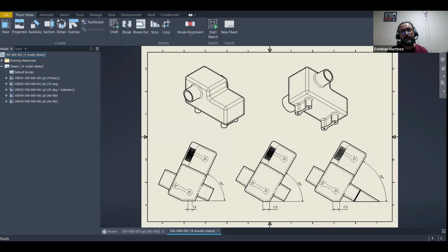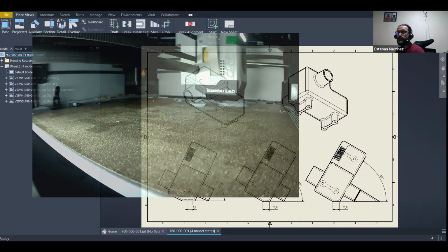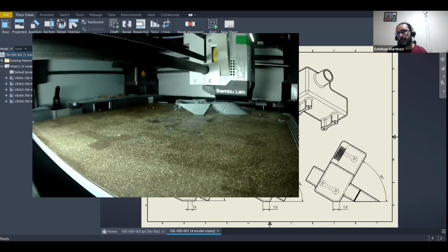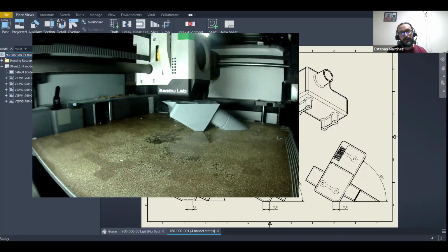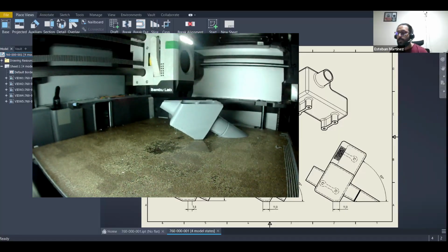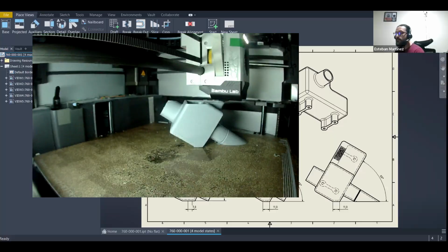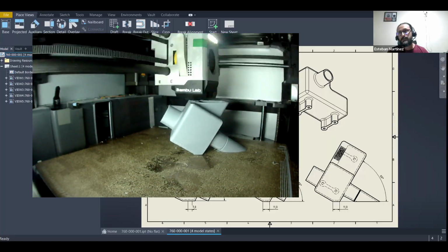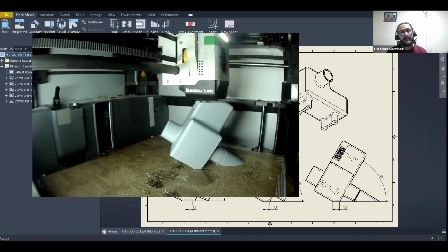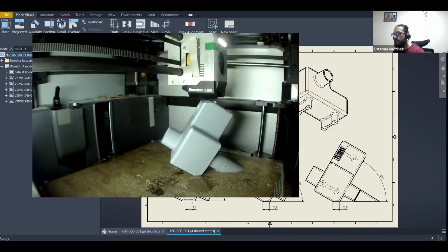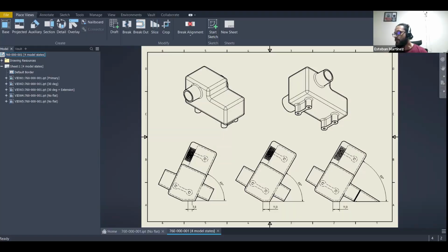The other challenge is the manufacturing method. You are running on 3D printers, so that's additive manufacturing compared to injection molding. And there are some things to take into account, like, well, overhangs is one of them, but also you need to take into account the finished surface, if you are going to have a thread.